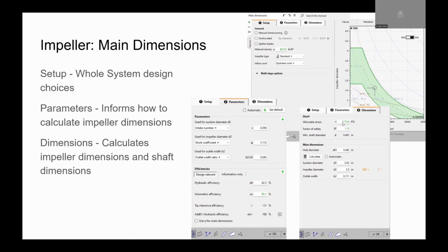Yes, this is based on steel, and then you basically take the power that you need to input into the impeller, and you know your RPM, you know your power, so you can find your torque. And then based on your torque on the shaft and your material properties, you can find the minimum shaft diameter. And then I have a Python script that does some of this math, and it checks out. It's just basic 204 math.